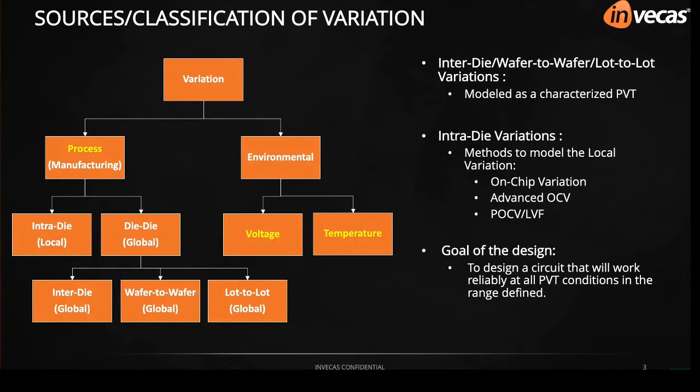Just to start with the conventional way of doing an STA sign-off, engineers will use the dot lib to do the STA, and once all the timing results are clean, they go for the tapeout. After the silicon comes back, surprisingly some of the chips start failing even after fixing all the timing violations, and it is happening especially when the industry started moving towards the advanced technologies. Then the people started thinking about what is the reason for the failure and what is the root cause.